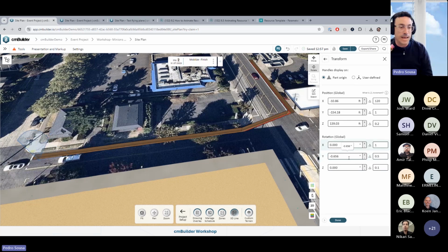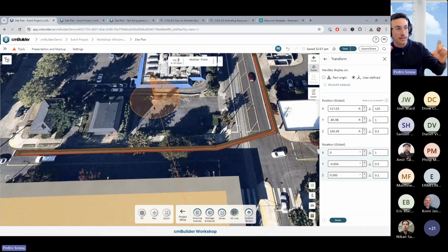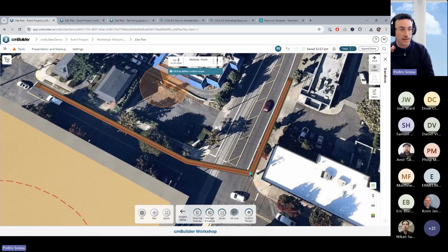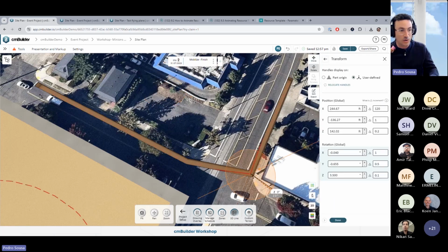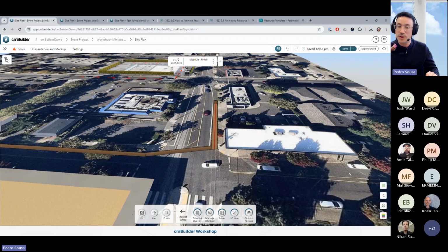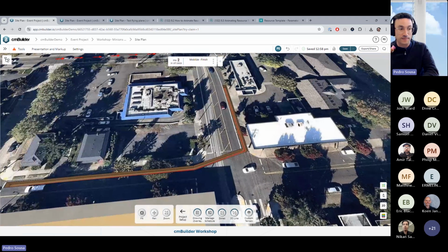So yeah, you can use the X rotation as well to move on the other rotation, but keep in mind that these rotations are applied to a global definition. If you want a user-defined definition where these rotations will be applied, you can click over here and use the definition, and then you can locate this angle somewhere, and then you can rotate according to this point instead. Cool, like this. Okay, so this is our 3D line usage for controlling the pipes.